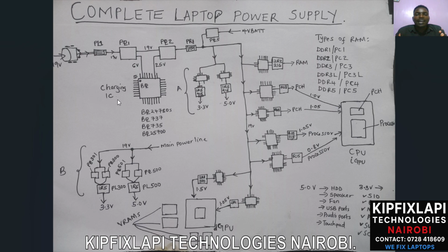So those laptops have what's called the TPS. TPS is the charging IC for those laptops which use Type-C. And those ICs which are used to control the Type-C ports are smart ICs, meaning in case you use a fake Type-C adapter, it might sense that the adapter is not the original one, and it might short that IC. So you need to be careful whenever you're using Type-C adapters.